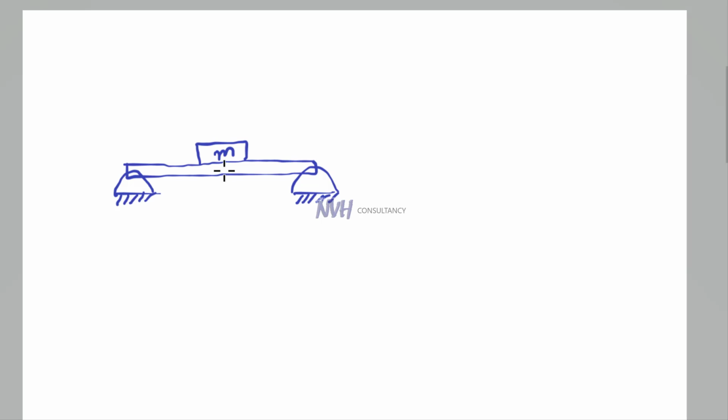and this is attached to the spring, which is again attached to the ground. So the spring has stiffness K. The material properties of this beam are EI, modulus of elasticity and moment of inertia. The mass is attached at the center of the beam. So if the beam length is L, then the mass from each end of the beam is at a distance of L by 2.